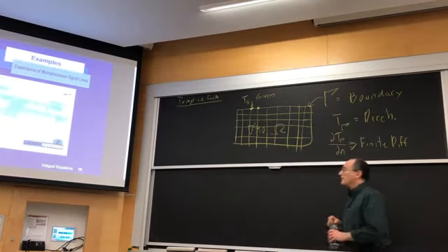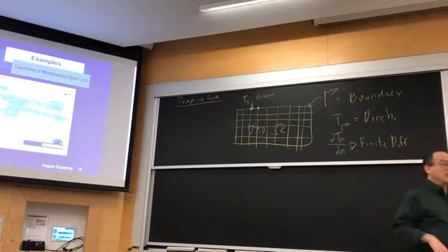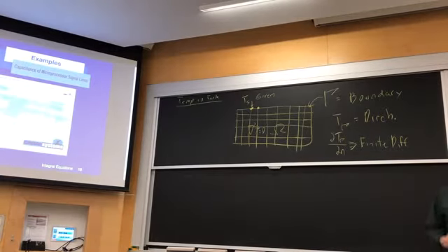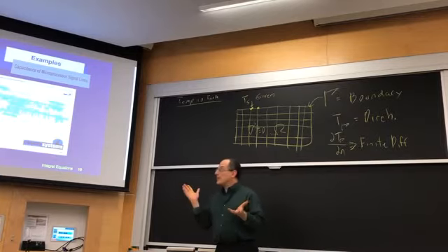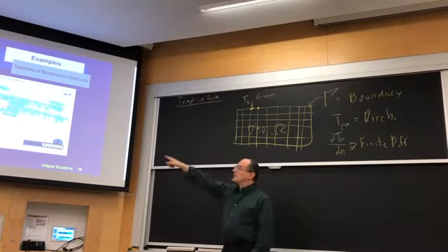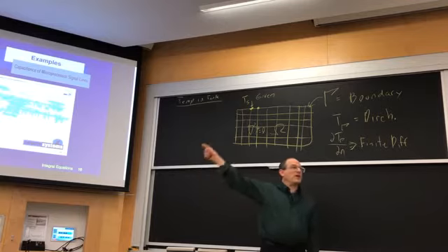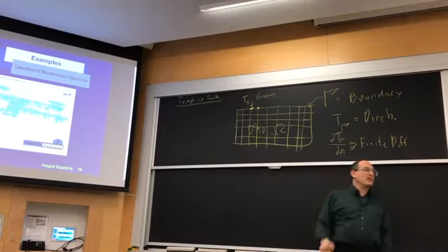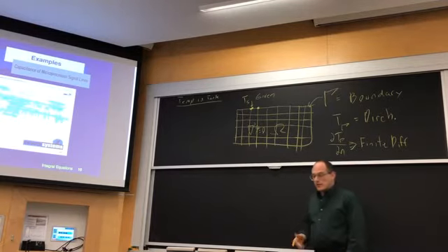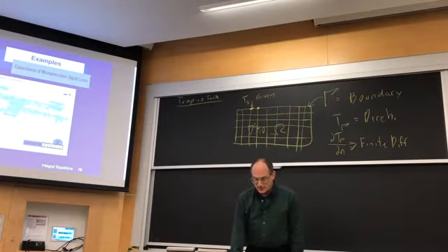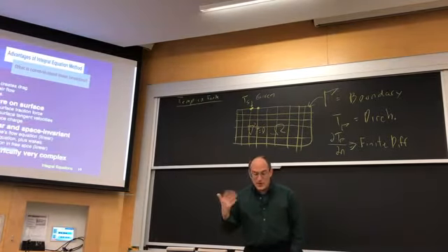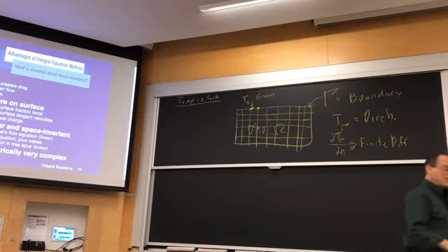And this is the surface of an integrated circuit. People who do capacitance calculations to figure out how fast a microprocessor is going to be extract capacitance from these very complicated geometries. It's hard to see here, but there are about 10,000 little green wires. They're all part of one interconnect. It's a signal being sent out in a microprocessor, and they use what are called fast methods to do these kinds of calculations. All of them are exterior problems.